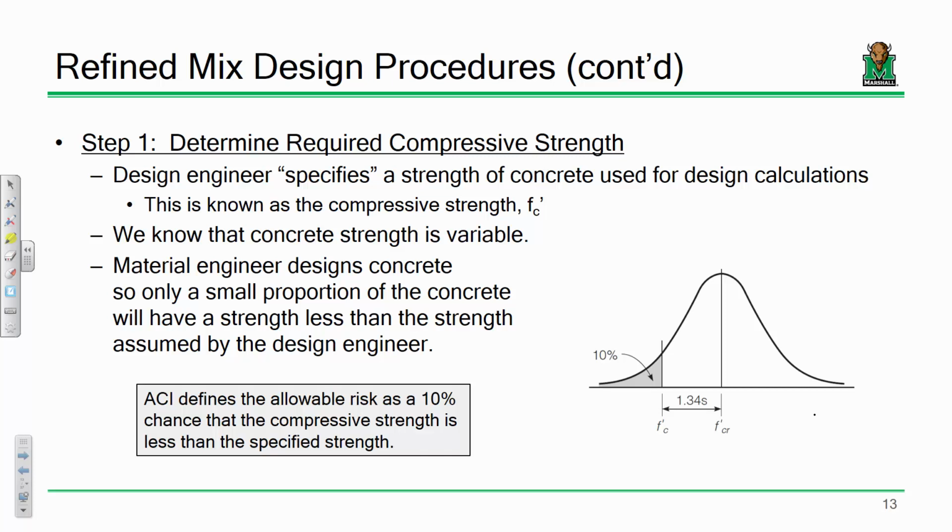And if you've had that class, one of the things you'll remember is that one of the very first values we assume about a given concrete design problem is FC prime. Now, FC prime is the compressive strength of a given batch of concrete. What I mean is, we're going to go into the lab and bust some cubes. We take a cube, compress it, and go till boom, till it fails.